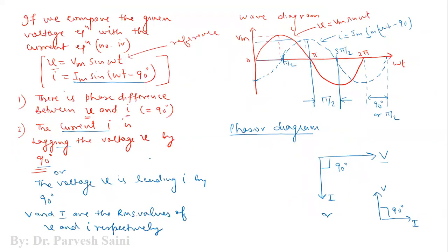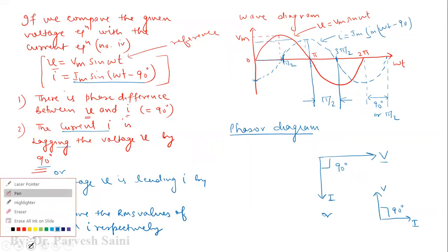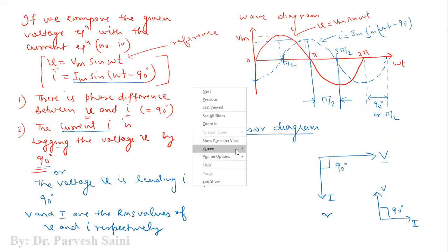Now if you compare, as far as your Ohm's law is concerned, let us take that equation. Let us erase all this ink from here. So you have this. As it is mentioned, Im is equal to Vm by omega L. Now what is this omega L? Now if you see, this can be written as Vm is equal to Im omega L. So this is somewhat resembling the Ohm's law equation, like V is equal to IR.